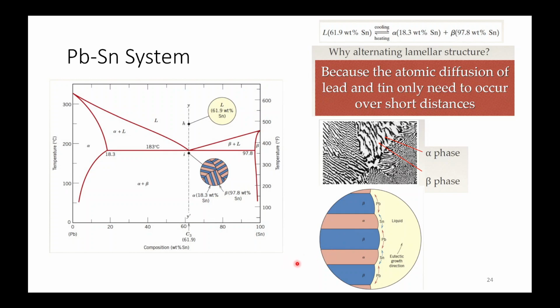Will these two phases be separated by grain boundaries, or will they be inside a single crystal? I mean, if we are taking any BCC or FCC structure, the alloying elements will be getting inside that crystal, isn't it? No, pearlite is a phase mixture. Okay, so this can have a single grain as well. In a single grain, your complete pearlite can be, but this alpha and Fe3C will have a physical boundary, a phase boundary.